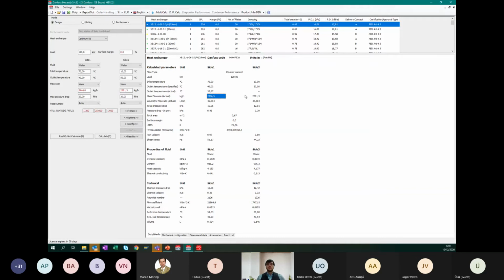One of the most important things I also want to highlight is the fact that domestic hot water capacities also need to be calculated in the right way, because we are still sometimes using district heating network recommendations or regulations and norms, which lead to a serious over-dimensioning of the domestic hot water design capacity. And I would like to go back to my slide deck just to briefly show you that.